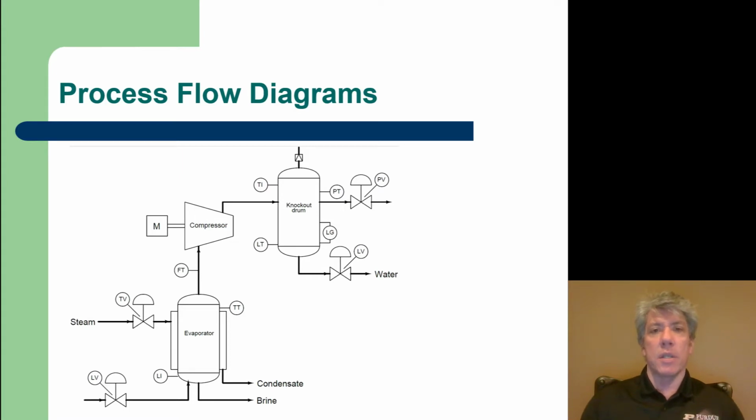When you have process steam, the energy storage that you give off is a phase change. It's a latent heat of vaporization. And so what that means is that it comes in as a gas, as gaseous water we call steam, and you don't want it to leave unless it leaves as liquid water, because you want it to give up all of the energy that it can, and it's primarily the phase transformation that's giving up energy.